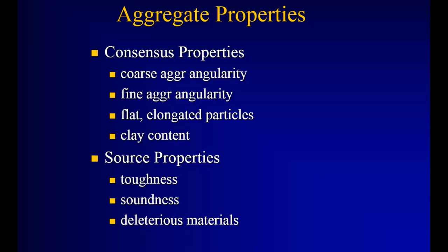And shorthand term is FAA, fine aggregate angularity. And in the Superpave world, FAA measures the angular nature of the material, the texture of the material. And in North Dakota, that becomes extremely important because we don't have a lot of the item above, the coarse aggregate, because we run out of all sand and gravel pits basically in North Dakota. There's no quarries in North Dakota.